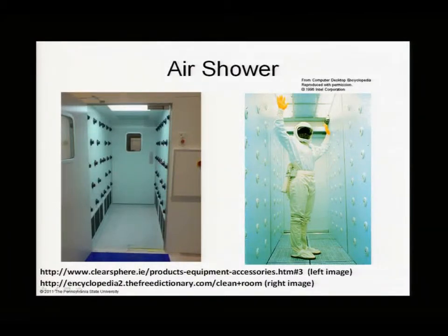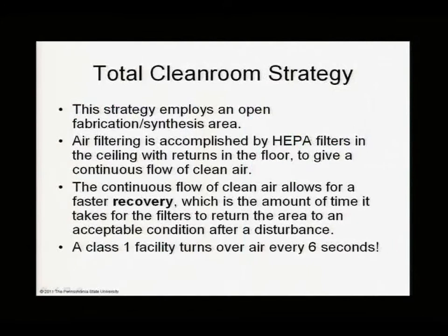The air shower. This is the air shower we were talking about. It's a shower, but not with liquid. It's a shower with gas, and the showering blows off any particles that may be present even after you've put on the full attire. So the clean room is a real special environment. You work really hard to get the humans ready to go in, and you work really hard to keep the equipment such that it is not contributing to contamination.